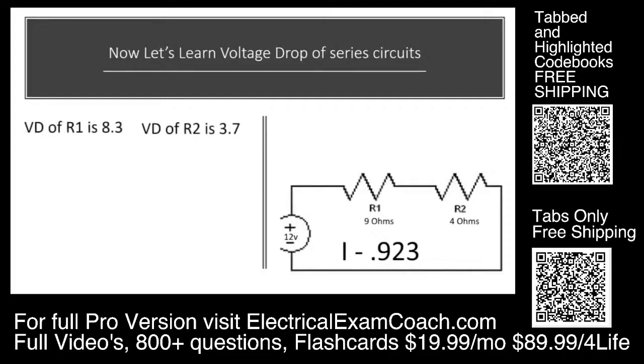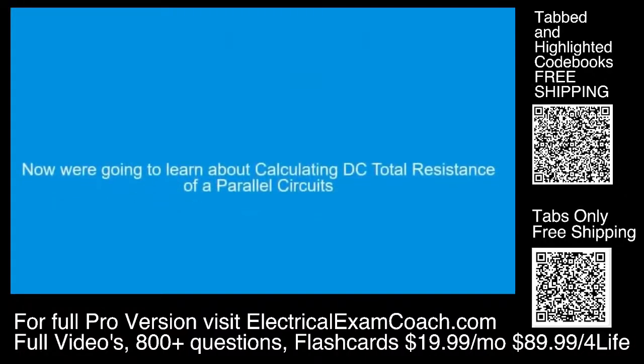The voltage drop of R1 is 8.3. The voltage drop of R2 is 3.7. 8.3 plus 3.7 is going to equal 12 volts. The voltage will be equal to the sum of the voltage drop across all resistors, and that's how you double check your work. Now we're going to learn about calculating DC total resistance of parallel circuits.